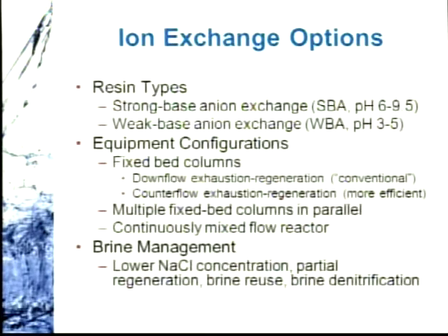You can do counter-flow exhaustion regeneration, where you have, again, treated water going top to bottom in a downflow mode, and then the regenerant itself is going from bottom to top. The theory behind that is if you are loading the contaminants from the top down, they're most concentrated at the top, so rather than trying to push them all the way through the resin bed itself, you just push them back out the shortest path possible.